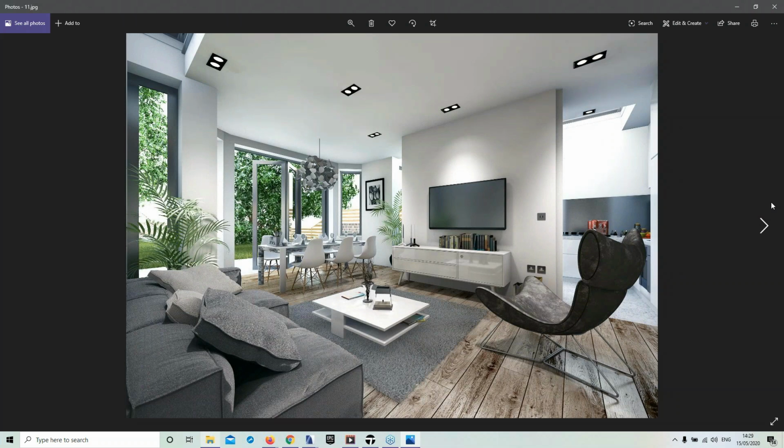Some interior design solutions, used the garden, and we're using only the internal ARCHICAD capabilities. And the foliage, for example, you can see in the background is all through the ARCHICAD models. There are various tips and tricks to make them look good, because normal ARCHICAD models do not look that good in the default mode, but you can tweak them, and there are ways. I can show you very quickly a quick way to do it.